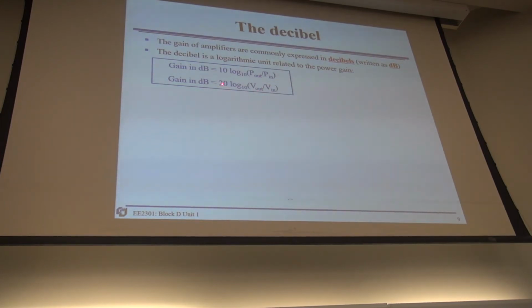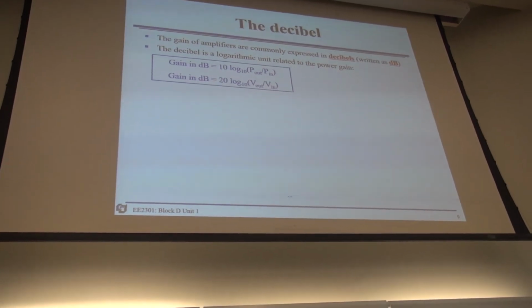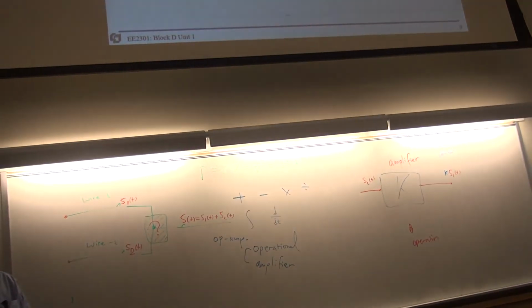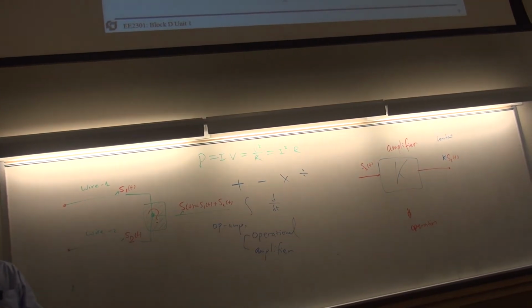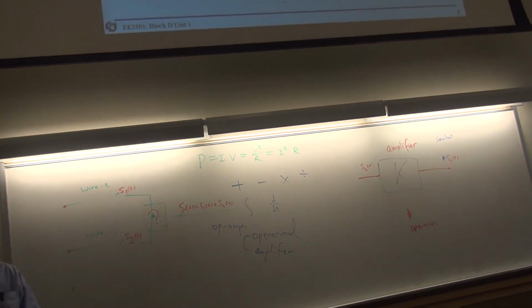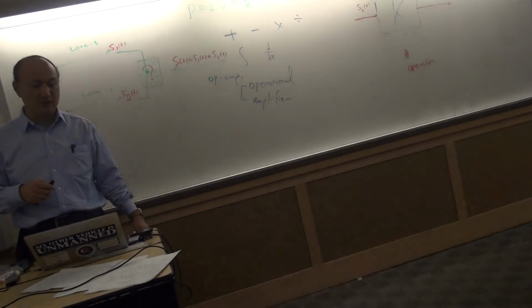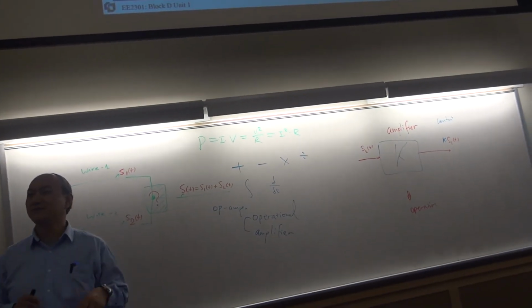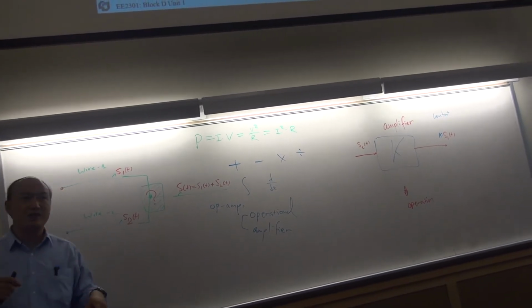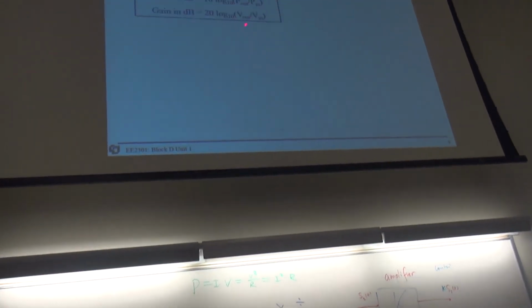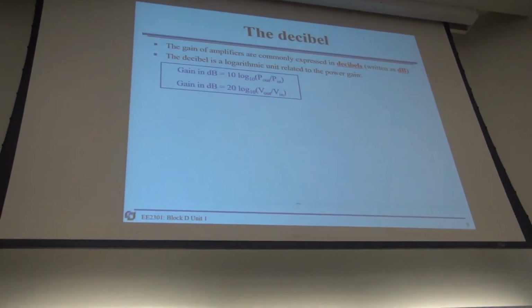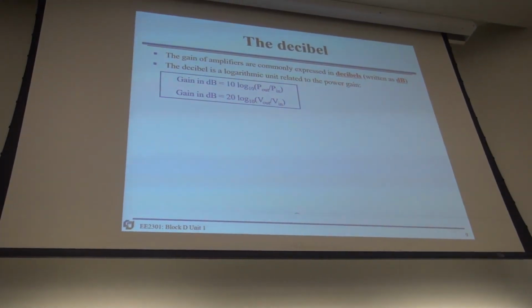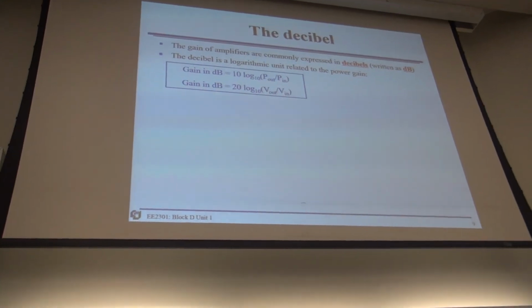So where is this 2 from? From here. The 2 is from here. So log V squared is 2, right? So it's 2 is from here. Or here. Either way. So I and V is called signals. And this is the power. So any questions at this point? So in the future, when you see 20 log 10 of the signal ratio, you should understand it is 10 log 10 power ratio. Is this clear?